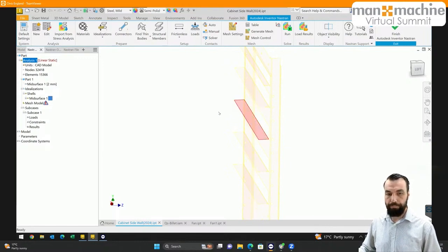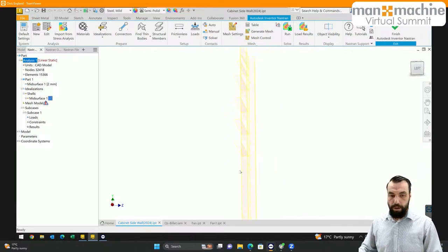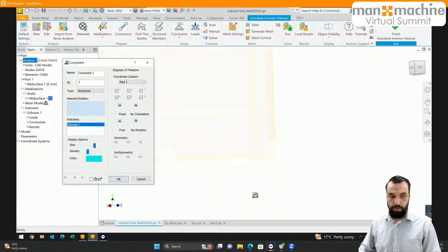We have some UPSs and batteries that sit on these shelves. It is part of a much larger structure, and obviously has framework and all the rest going about it. But we just wanted to test that these sheet metal folds would not fail underneath the stress. So I'm going to start setting it up by adding constraints at the bottom, and we'll choose the normal fully fixed constraints.